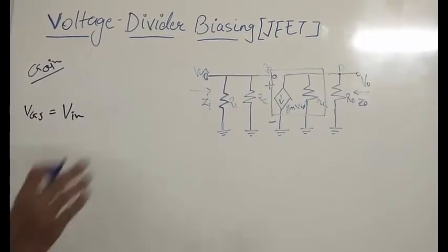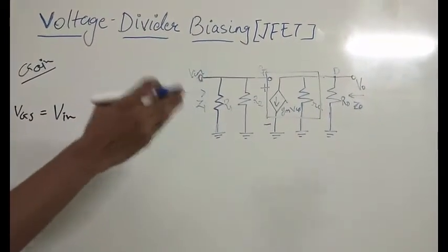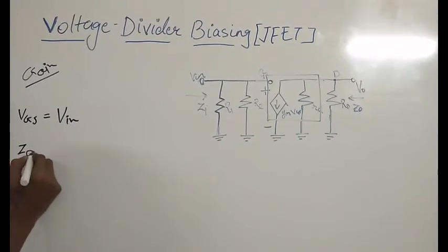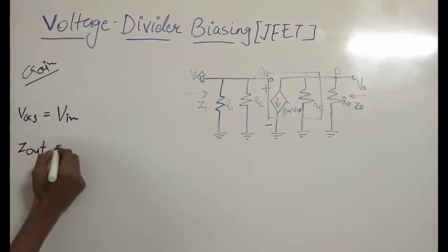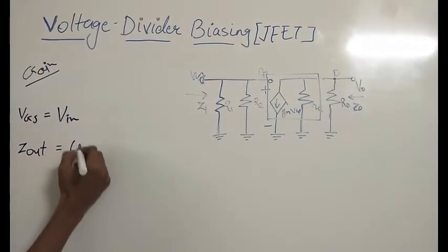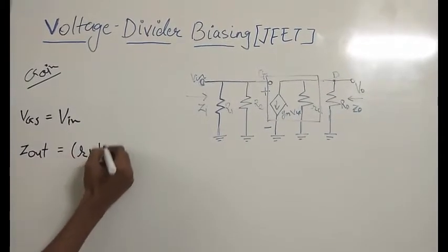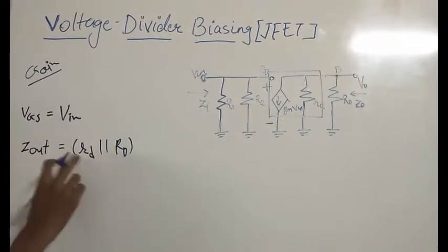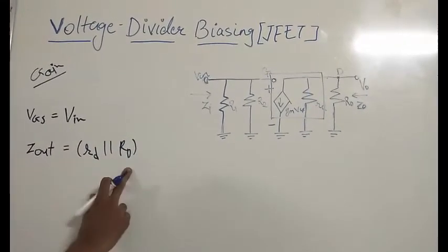Also, the output impedance is equal to small rd parallel with capital RD.